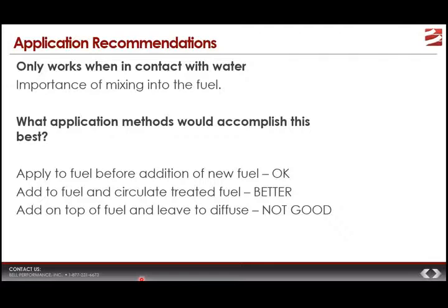Now, some people have gone what we should say the cheap way, or the easy way, which is they just add it on top of the fuel and leave it to diffuse through the fuel. This is not a good way to add DFS Plus because eventually it's going to reach the water. Remember, it's on the bottom of the tank. Eventually it's going to reach the water, but it's not really going to have the kind of effect that you're expecting if you've made the decision to use it. And so, in that kind of scenario, you might think, well, it's not working. Well, it does work. It's just that it wasn't applied as recommended.